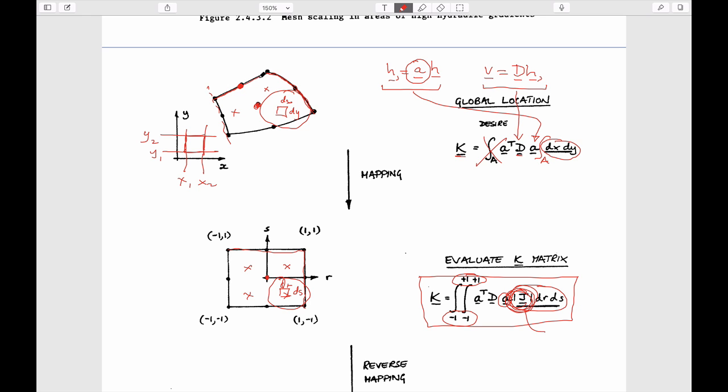And we want to be able to map it using some other method. And so the method we use is to map it onto this 1 by 1 square in 2 dimensions, or in our particular one-dimensional case, it was just a linear element which was +1, -1, and 0 in the middle that had nodes at each end.